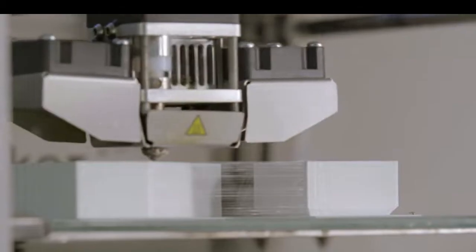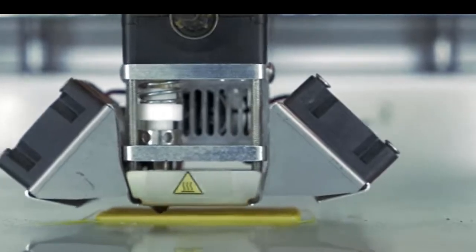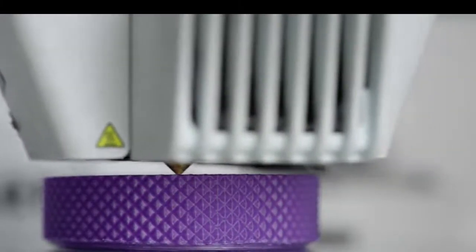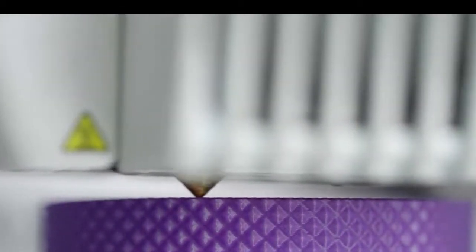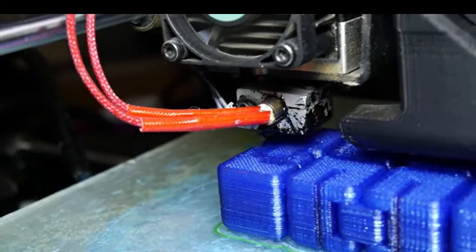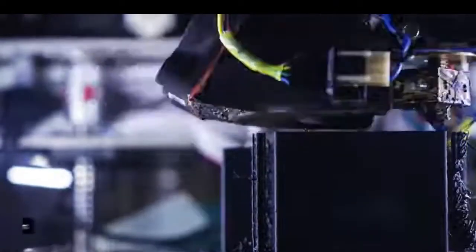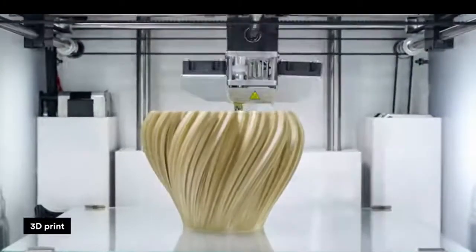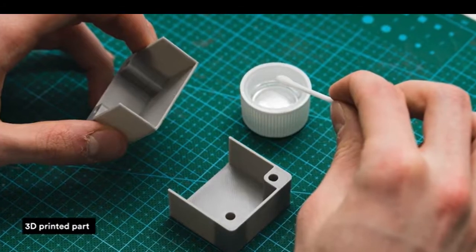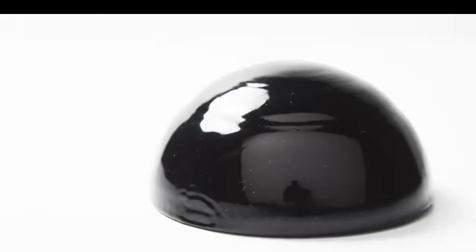From here, the way a 3D printer works varies by process. For example, desktop FDM printers melt plastic filaments and lay them down onto the print platform through a nozzle. Large industrial SLS 3D printers use a laser to melt thin layers of metal or plastic powders. Plastics are by far the most common, but metals can also be 3D printed. Depending on the size of the part and type of 3D printer, a 3D print usually takes about 4 to 18 hours to complete. However, 3D printed parts often require some post-processing to achieve the desired level of surface finish.